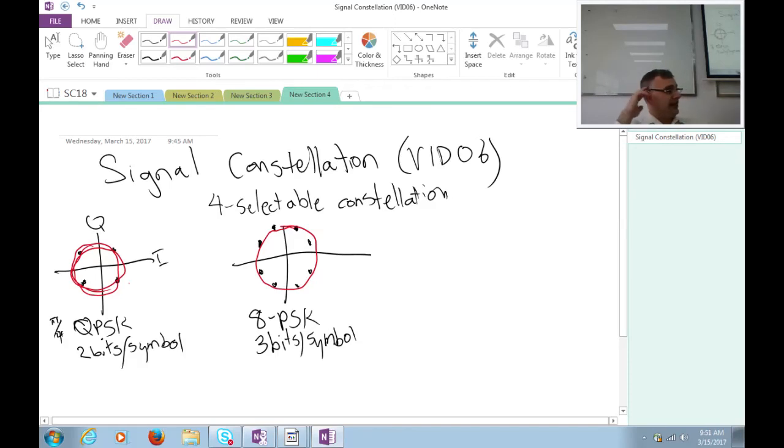This is particularly true for satellites because some satellites, in order to accommodate high power levels, will use things like traveling wave tube amplifiers and other types of amplifiers that have extra nonlinearities compared to a standard solid state amplifier. The amplitude of the signal will actually fluctuate. It can fluctuate away; for these two constellation signals, that's not going to change anything.